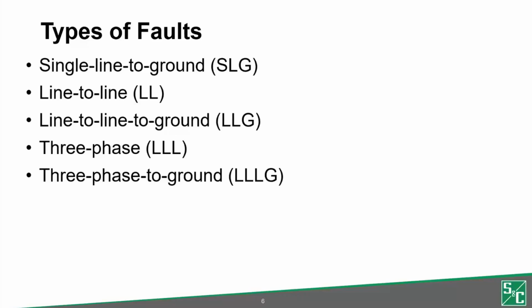In order to perform an overcurrent coordination study, the first step would be to perform a short circuit study. The reason being that we need to ensure that coordination between two series devices is maintained for all types of faults, right up to the maximum fault current level expected.